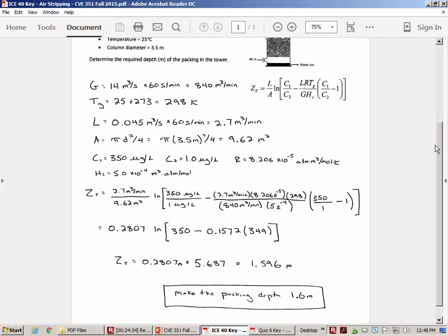So this is just one of the methods that's used for remediation. It's really interesting to see all the genius ideas people have come up with to figure out how to deal with contaminated soil and contaminated water. It's everything from using gigantic electrodes and literally turning the contaminated soil into a big block of glass. And that's a process called in situ vitrification. Very, very high voltage electrodes can immobilize a pollutant and make it so that it's not going to leach into the soil anywhere.